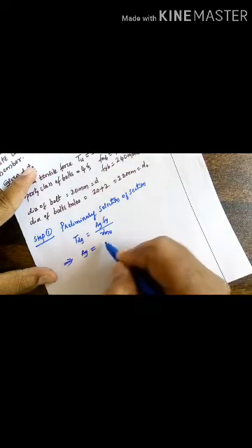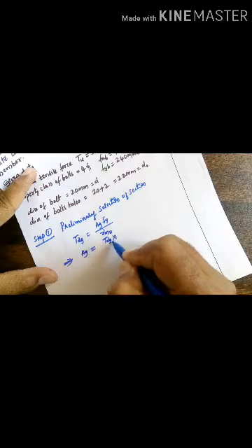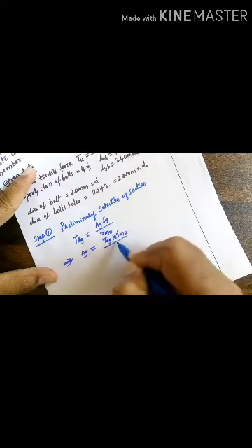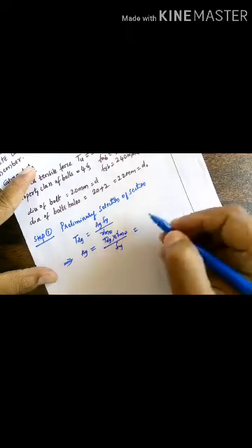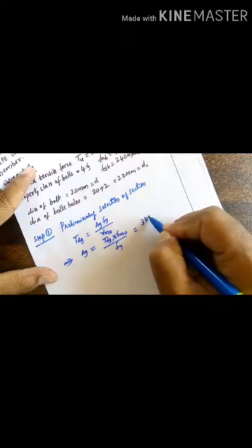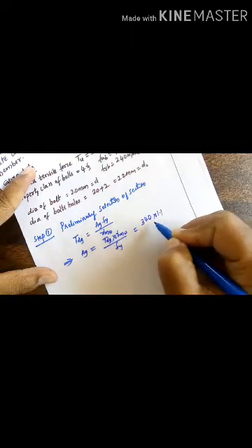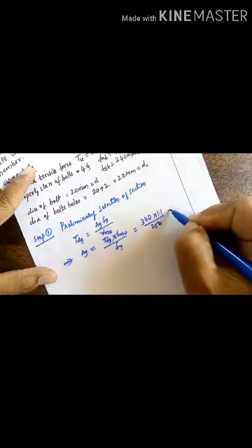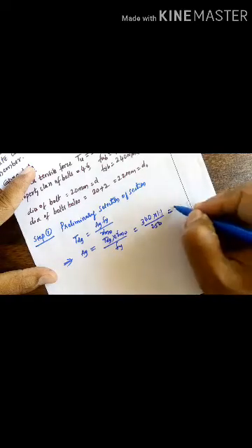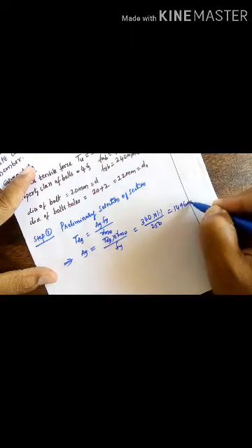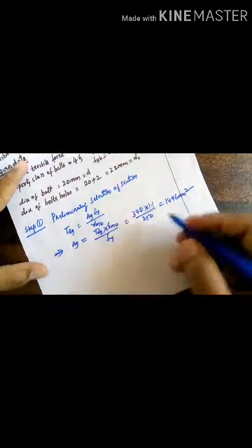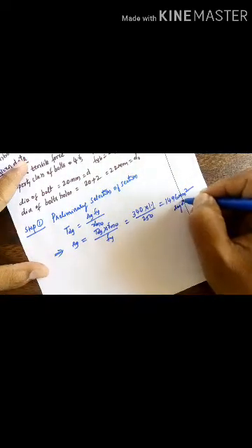Az will be Tdz into gamma m0 divided by Fy. Tdz is 340, that is the factored load, into 1.1 divided by 250. You get an area of 1496 millimeter square. So this much is the required area,